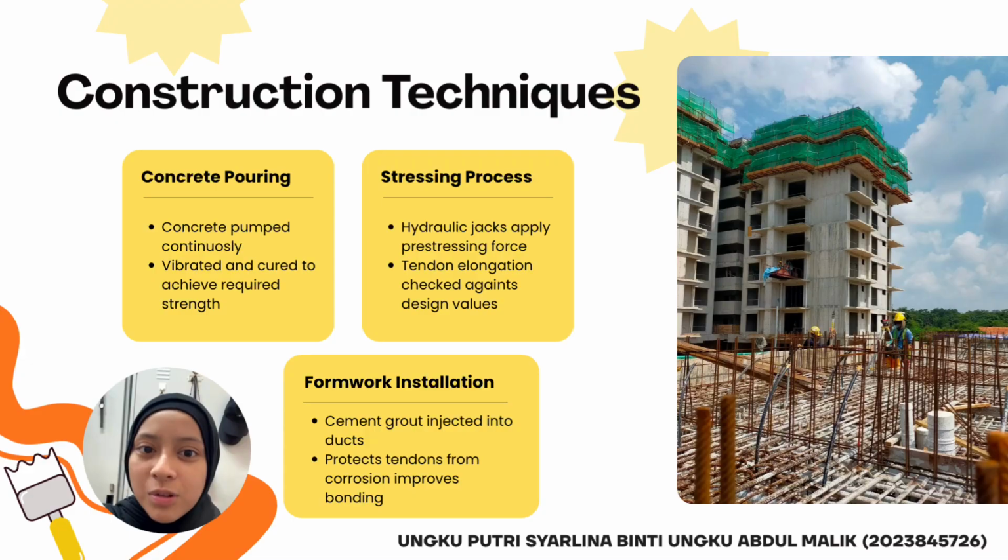And after all the reinforcement and tendons are complete, the concrete is finally poured. The concrete is pumped continuously, and it is also compacted and cured until it reaches the required strength. Next, the stressing process: the tendons are then stressed using hydraulic jacks, and the elongation is checked